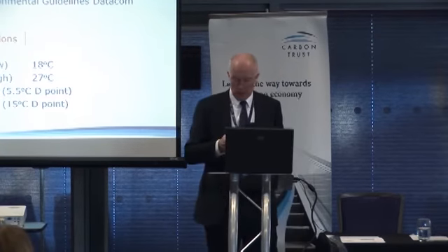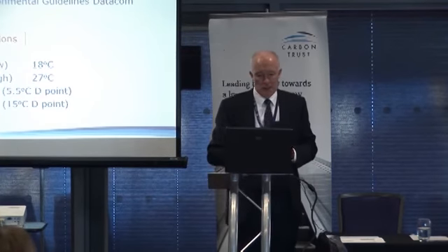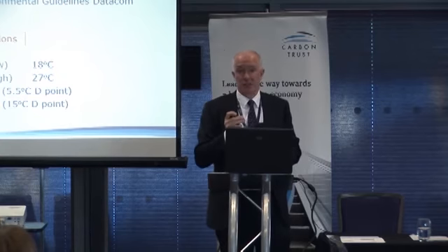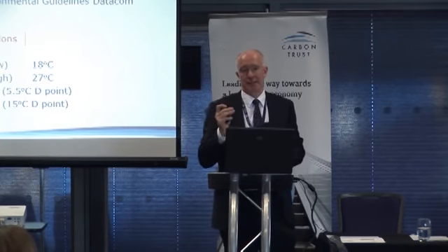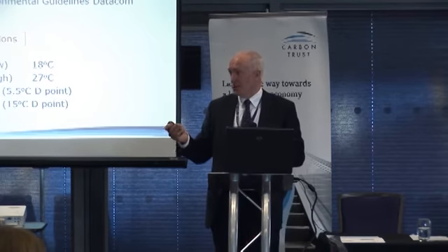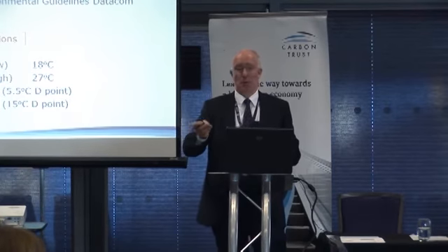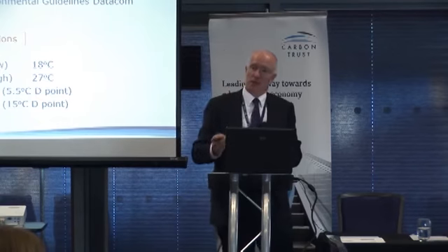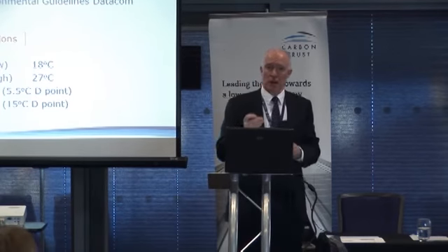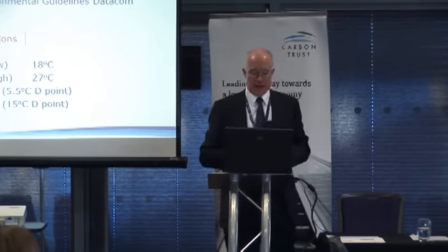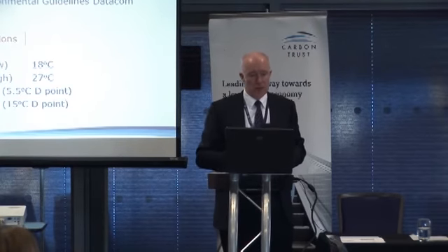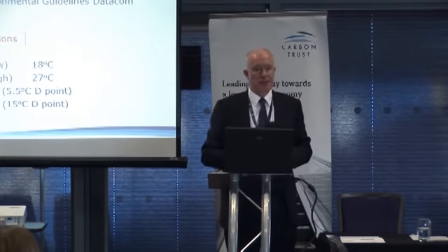So that thought process is quite important to talk to them. What are we talking about? Well, the ASHRAE standards are saying that the lowest we should go to prevent any problems with dew point is 18 degrees centigrade. So we don't want air less than 18 degrees centigrade, not colder than that. In many computer rooms that I go into, they're set to minimum. A minimum on direct expansion chilling is often 16 degrees centigrade, so you actually could cause harm to your computers at that level. The maximum temperature for most equipment is 27 degrees centigrade.